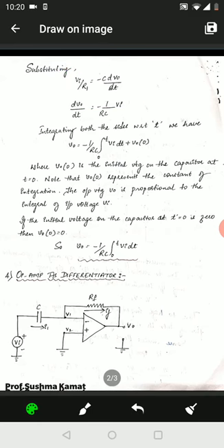we will now try to form it in this way that we will write the equation for dV0/dt. If we write the equation for dV0/dt, that minus C comes on the other side. If it is minus C coming on the other side, we will have the answer d/dt of V0 is equal to minus of 1 upon RC into Vi.